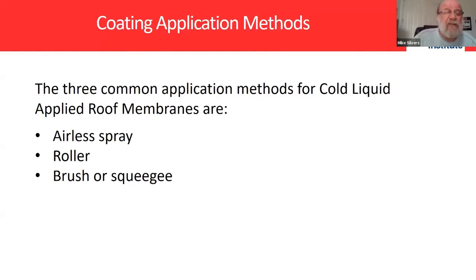Rollers, brushes, and squeegees, as you use them, if you're getting a good covering, chances are you're probably getting close to the millage you need. You obviously need to check. And a lot of that will depend on what type of product you're using, whether you're going to use one of these three systems. Most of them will work with any of the three, but particularly when you get to some of the real thick products, or if you're mixing a two-component system, you obviously have to have an airless that's capable of mixing those two components. So that's normally how they will go down.